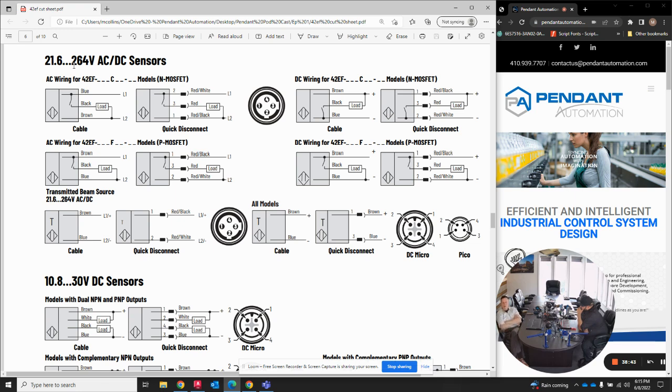And so I learned the hard way, and I've never actually confirmed this. I was just troubleshooting one time, and it was so ridiculous I had to get on the phone with tech support. But a MOSFET only controls the current, and it actually lets the voltage bleed through.